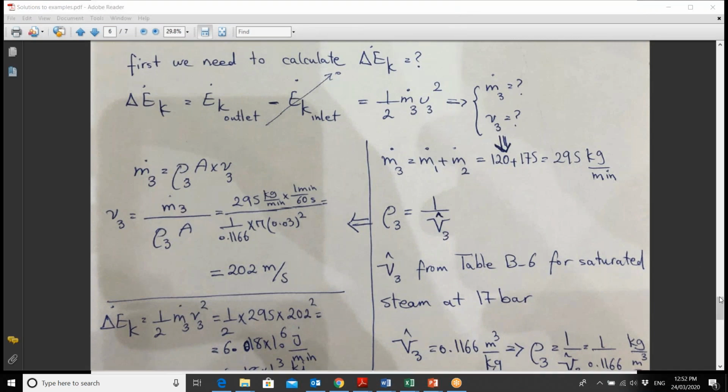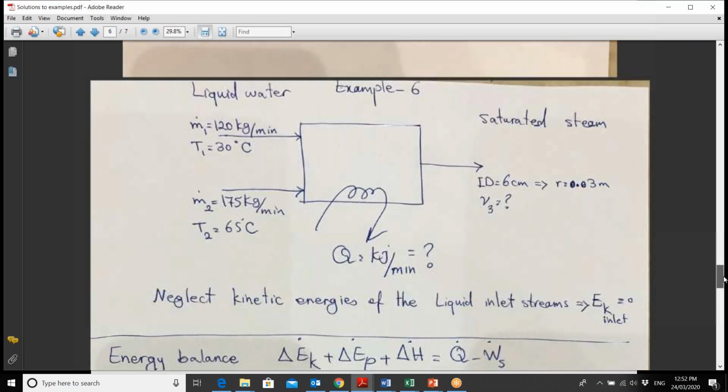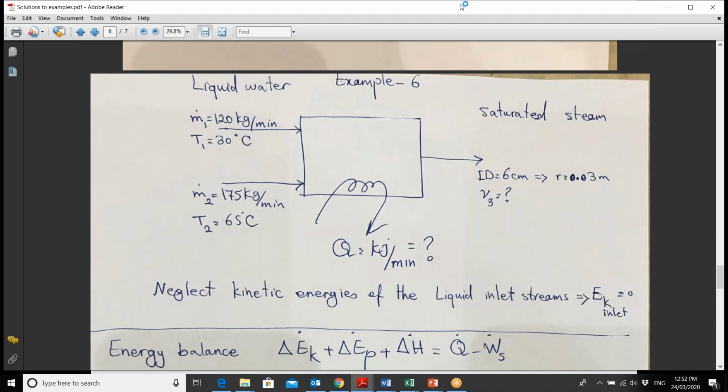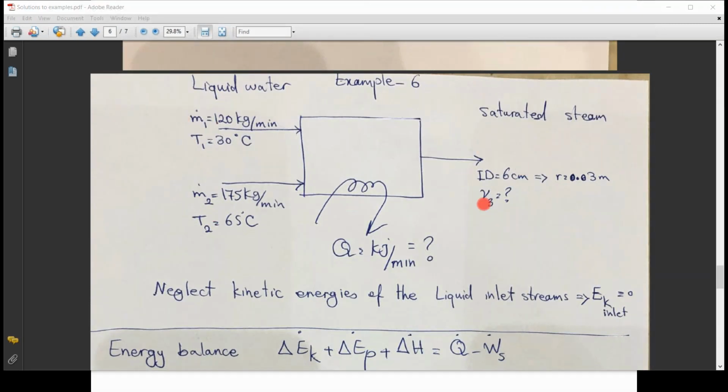Calculating the mass flow rate here is easy because you already have mass in. To be able to calculate the mass out, you just have to, because these two are adding to the boiler and exit at the outside. So mass out is equal to the sum of these two masses. Agree?